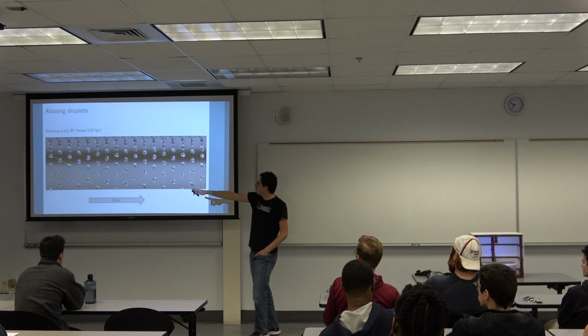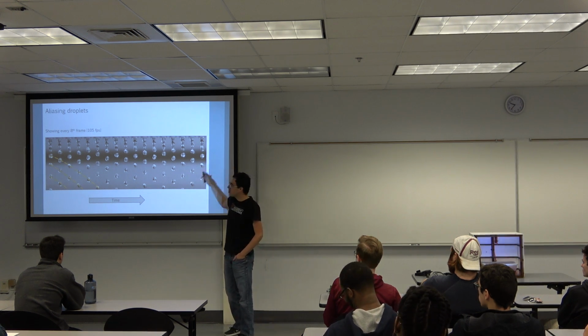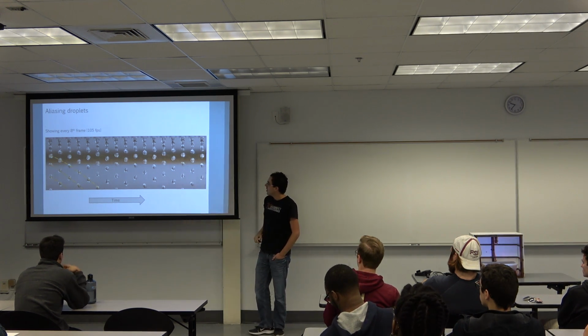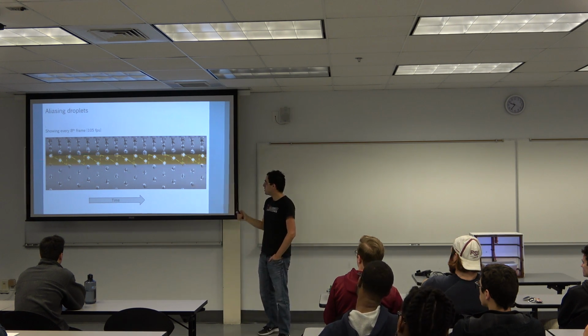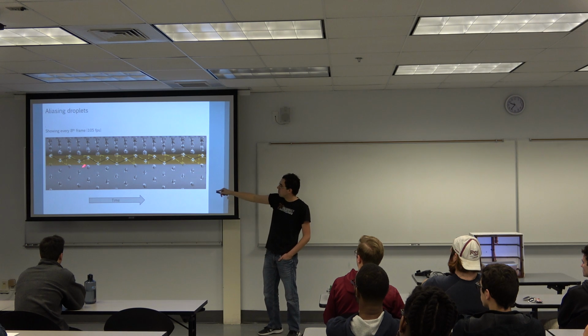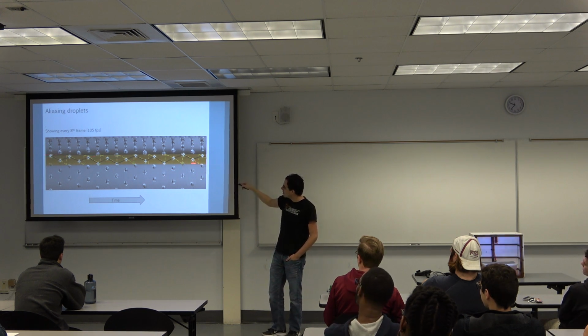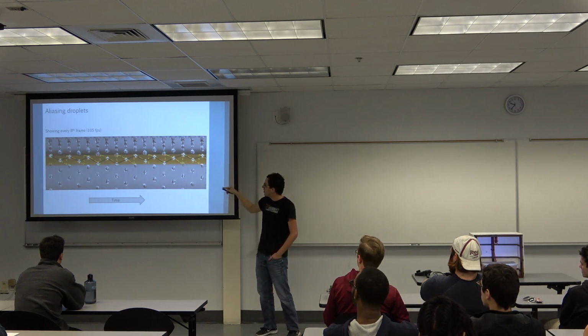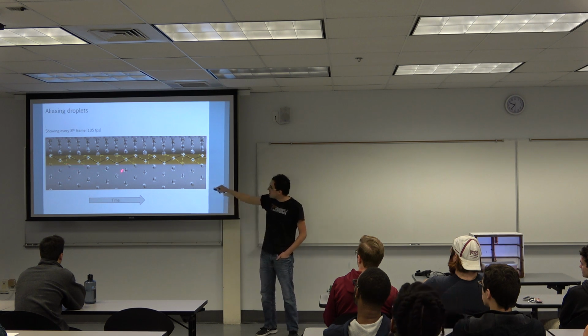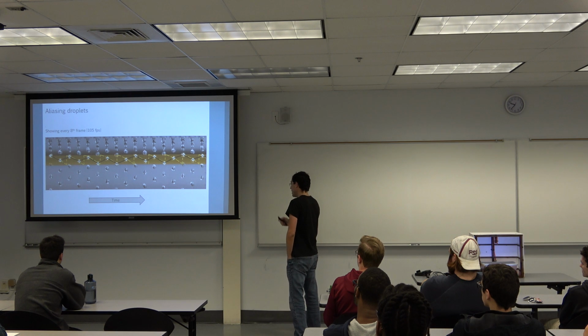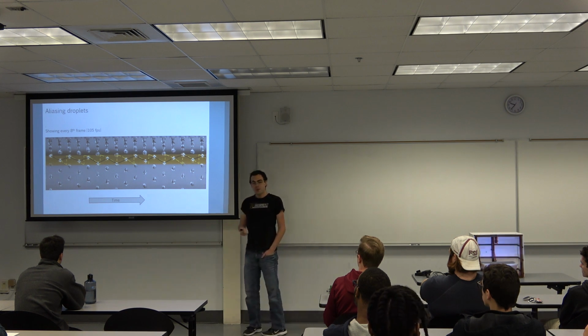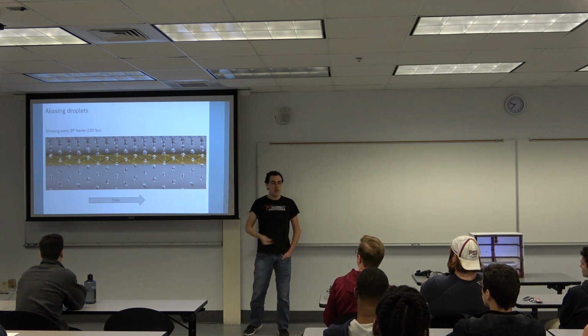And now if you look at the movie, it's kind of hard to see what direction the droplets are going. If we focus on the sawtooth waveform, you can see that we can get the frequency of the sawtooth right, but now it's a little bit difficult to understand what the wave is. It's very jagged because we only have 2 samples per cycle. So what's going to happen if we reduce the sampling rate even further?